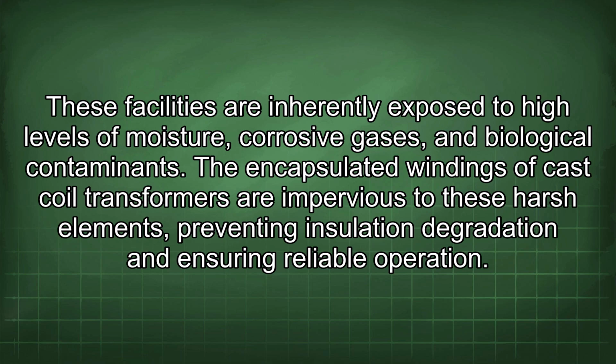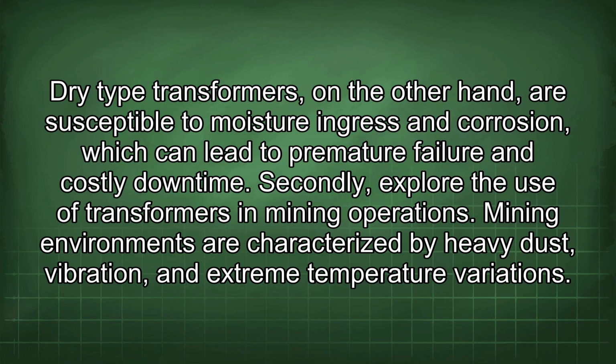The encapsulated windings of cast coil transformers are impervious to these harsh elements, preventing insulation degradation and ensuring reliable operation. Dry-type transformers, on the other hand, are susceptible to moisture ingress and corrosion, which can lead to premature failure and costly downtime.